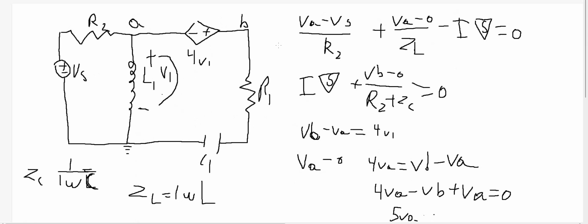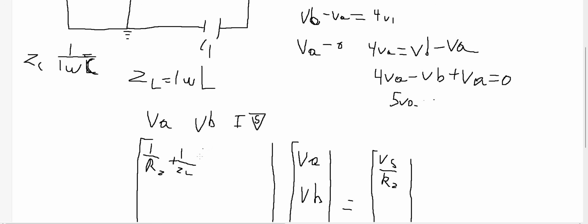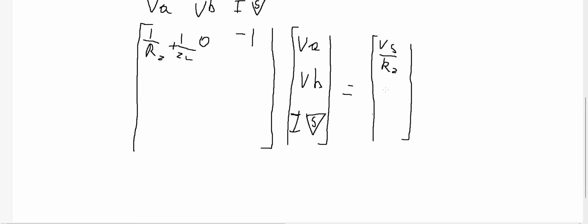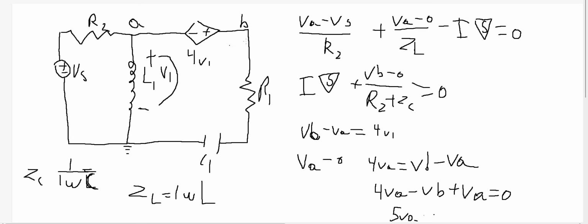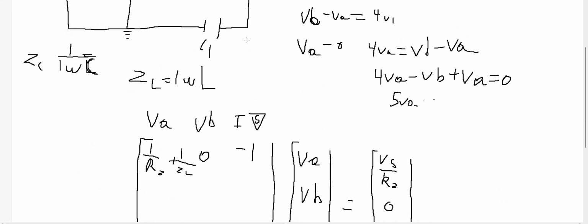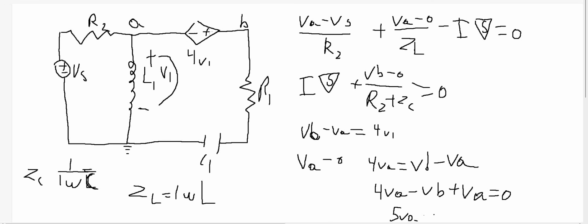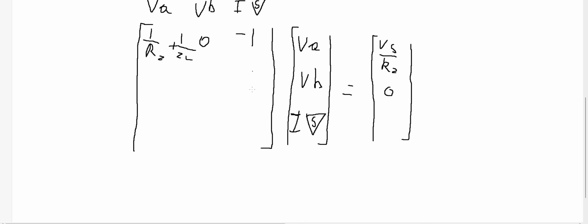So we're just seeing what we're multiplying VA with at this point. This does not actually contact VB, and it's a -1 relationship to IS. We can write a 0 here because there's no real voltage sources right there. It's only the supernode, which we're counting as this whole separate thing, and we're going to take care of that right here.